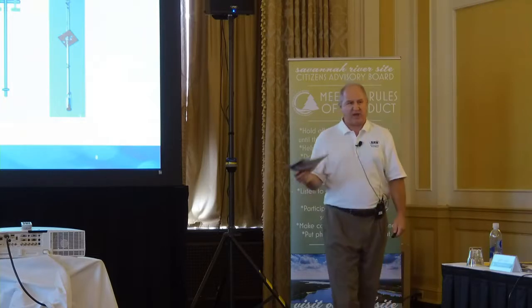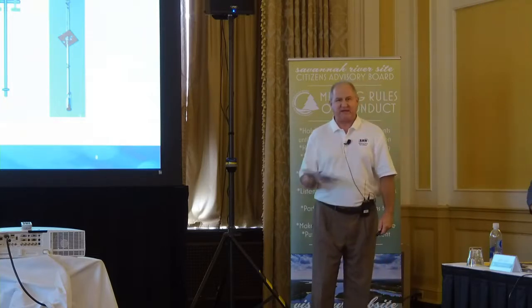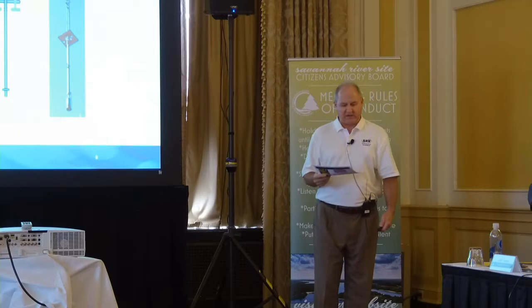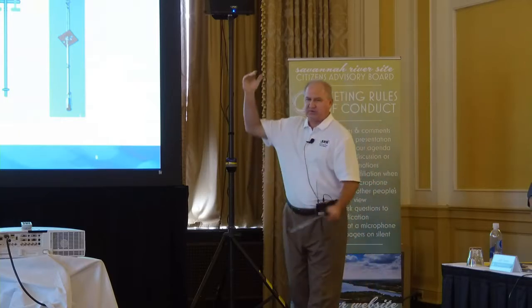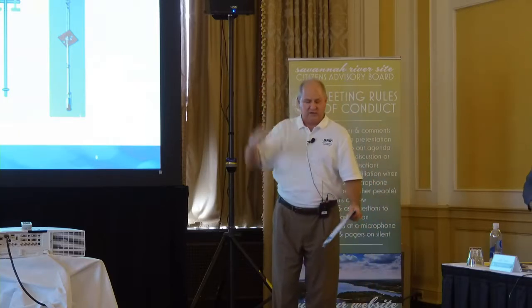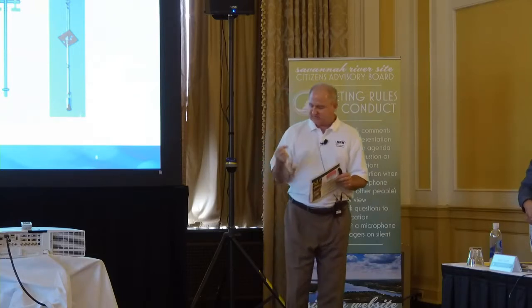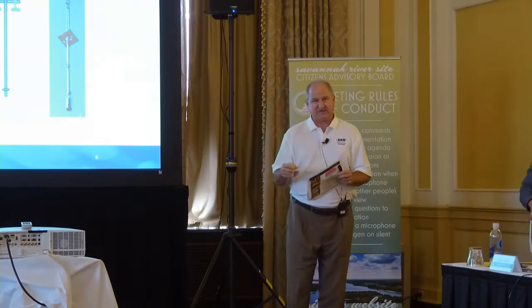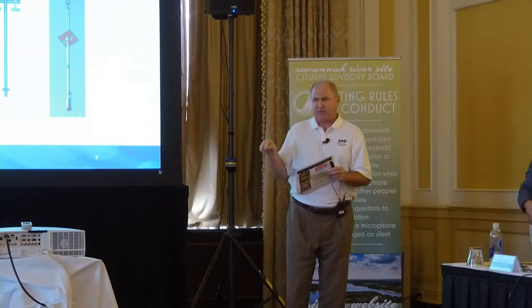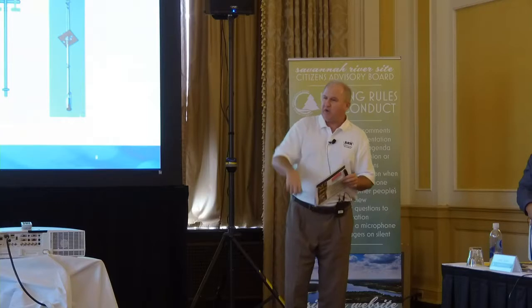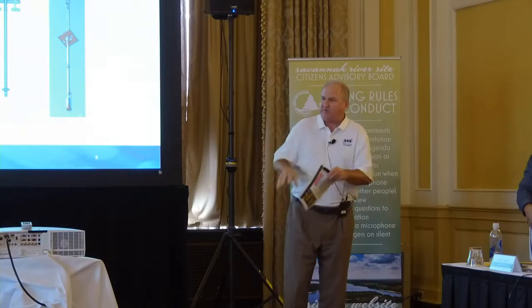Before we started batch 3, we made the decision to hydrolance the tank, and you may have heard of this. It is a technique that we use to break up heels and similar material. We take this long wand, and we put what we call a pineapple head at the bottom of it. It's about as big as your fist, and it's got different types of high pressure nozzles that point in different directions. So when you put it in the tank, it just shoots out all different ways.